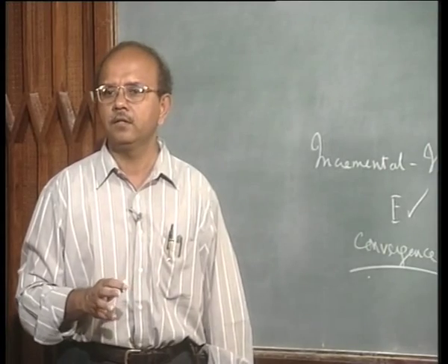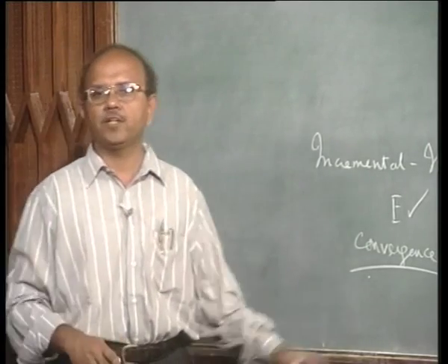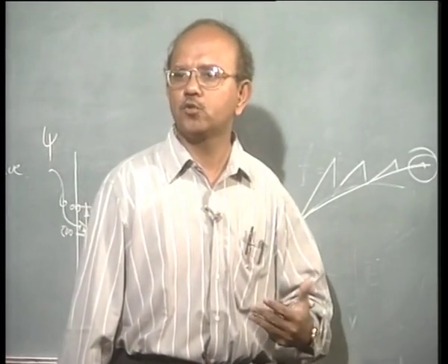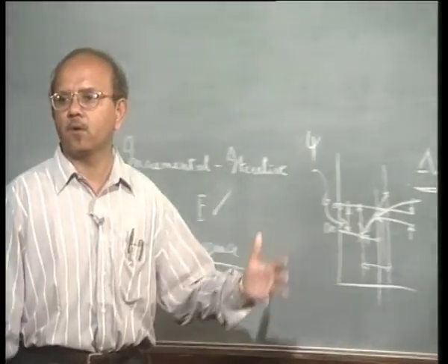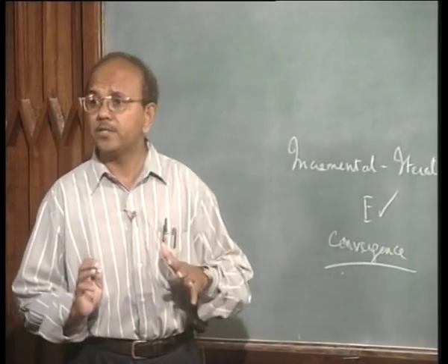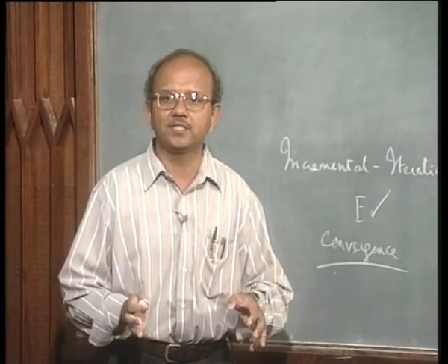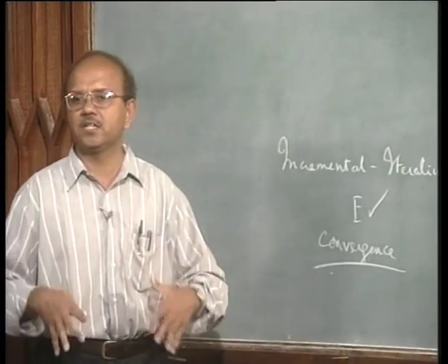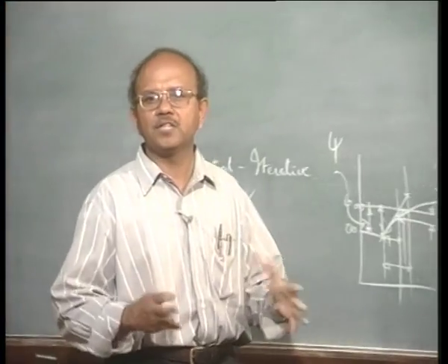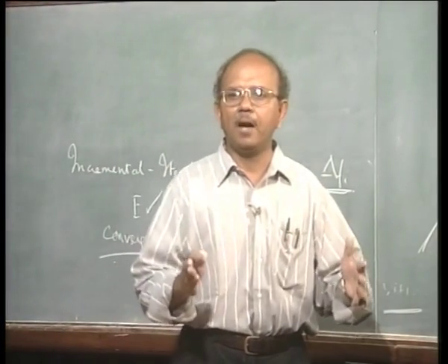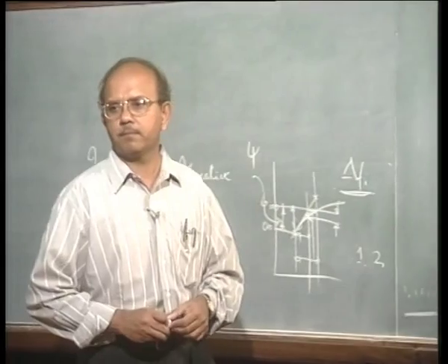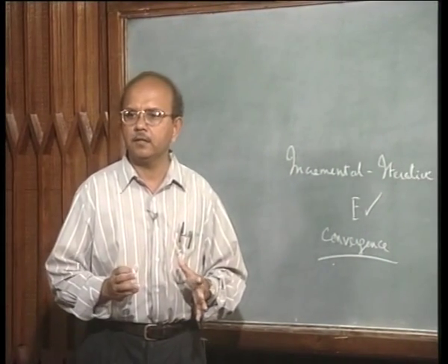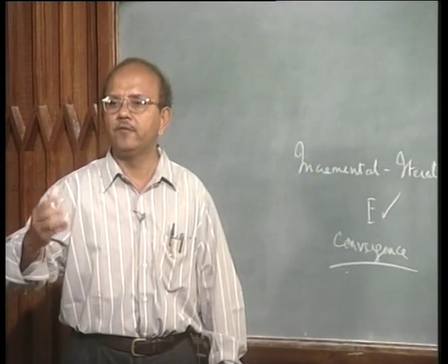Is this clear? So we follow what is called an incremental iterative approach in order to do a nonlinear problem, and we always look for convergence. The convergence is one which makes my stress, the internal stress, and hence the internal force equal to the externally applied load or force. Is that clear? So I keep on doing this for every load.